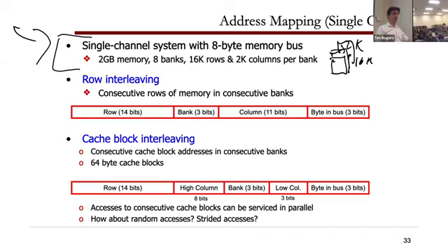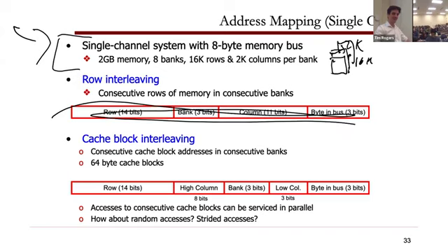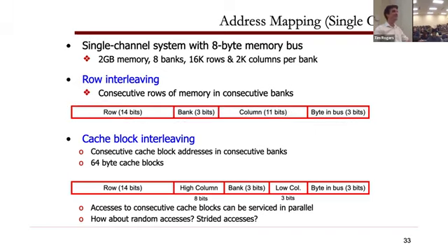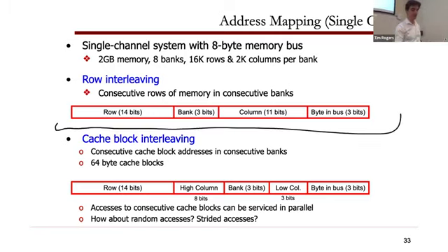31. How do you get 31? I added 1 gigabyte. Okay, that's one way. Yes, what's another way? If I didn't show you this picture, how could you know that you need 31 bits? 1 gigabyte is 30 bits. Yeah, 1 gigabyte is 30 bits, so a 2 gigabyte memory system needs 31. Okay. So the number of bits in the physical memory system is directly tied to the number of bytes that you actually have in your memory system, right? This is physical now. These are the things you actually can read and write to in the physical memory system. So I know that the total number of bits here needs to be 31.